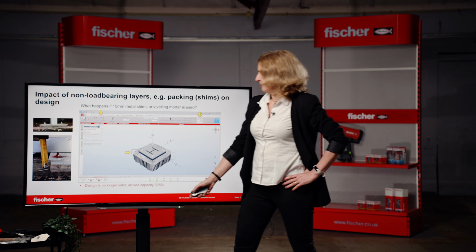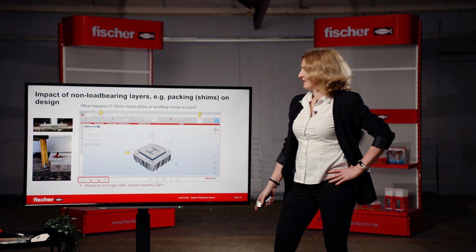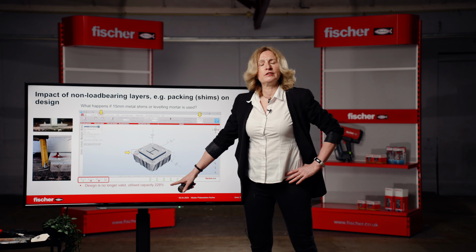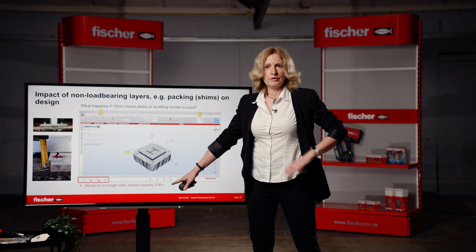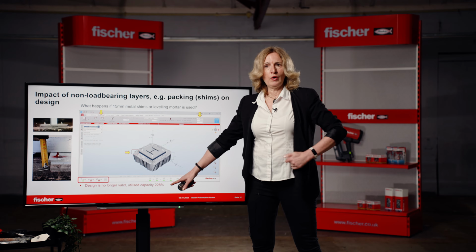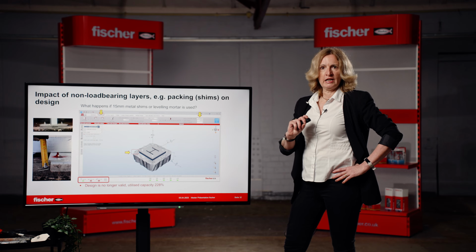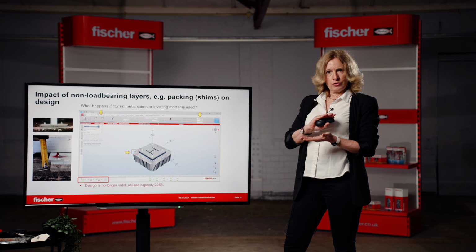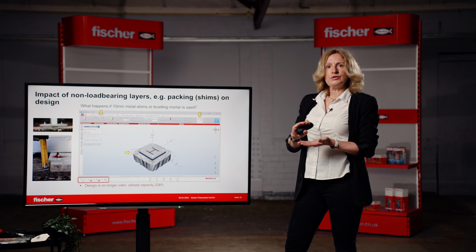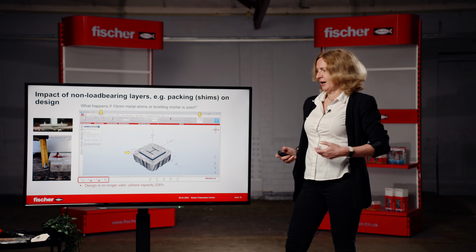And you will see that the design utilized capacity now is 228%. So from 40, we went to 228. That just shows how important it is to take this into account. If you have shear with non-load-bearing layers, you have to design it as shear with a lever arm.